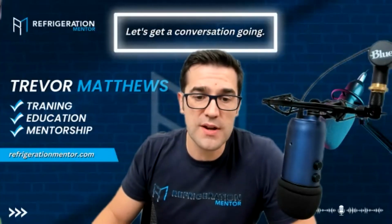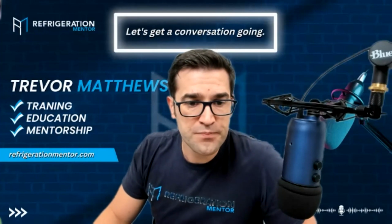What else could cause overheating, Bob? Well, a dirty condenser, I think, is probably one of the largest reasons. And that's a little more likely on that single compressor application, to an extent. But remember, when you've got that larger condenser, there's a little room for that. Those guys take care of those condensers pretty good. But it's that single condenser that seems to really give a problem.